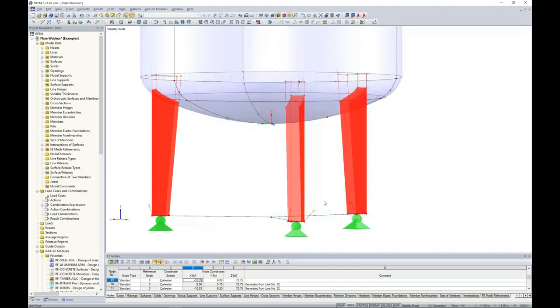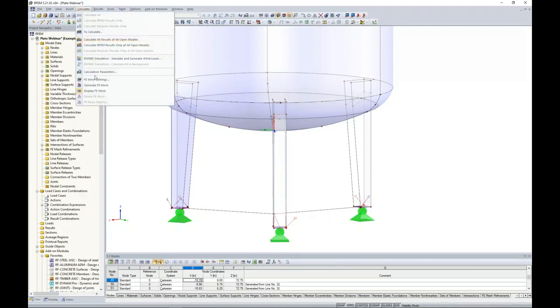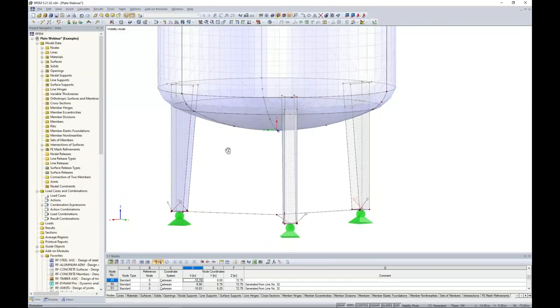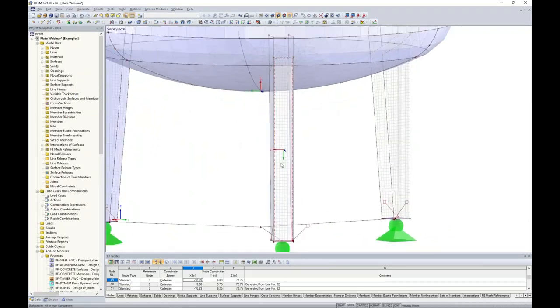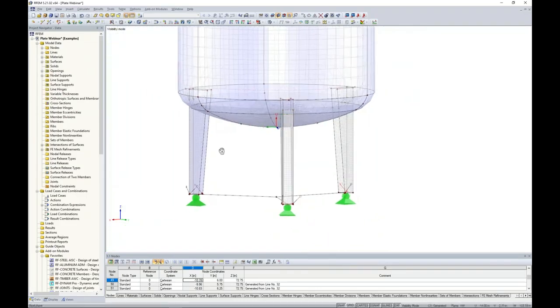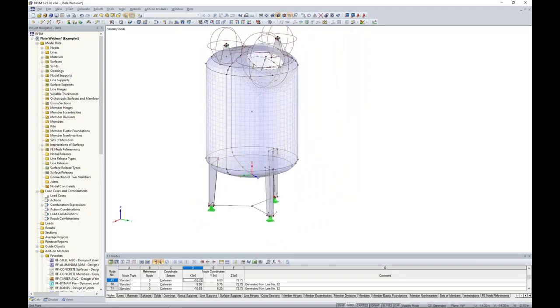The FE mesh refinement symbol is going to be shown as this little flag down here. So that's what is being displayed for my surface FE mesh refinement. I go to Calculate, Generate FE mesh. And now we can see that this FE mesh looks considerably better. It transitions quite nicely, again, back to that 2-inch length set for our global settings.